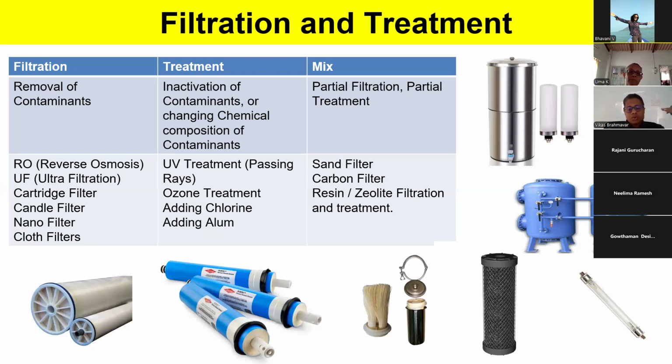Okay, there is ozone treatment, where it takes oxygen from air and converts it to O3, and it kills bacteria. It breaks open the virus fully. It doesn't just crack the layer, it breaks open the virus fully. So it takes generally 24 to 28 hours, some people say up to 36 hours, for the bacteria to regrow. So that can be used in places where someone uses the water within a day, so there won't be bacterial growth. So after UV, it's ozone. Some swimming pools use an ozone system instead of UV. For a point of use system, where in your kitchen you're just taking the tap, UV is sufficient to disinfect because you're consuming it right after.